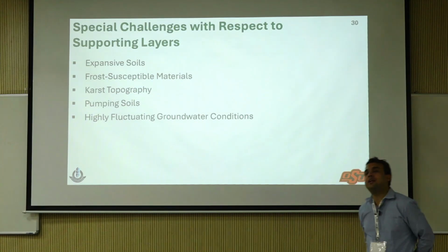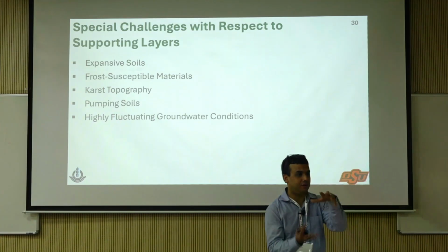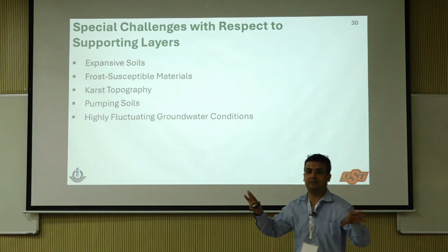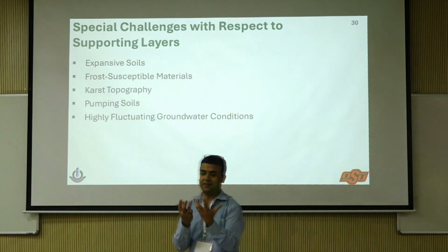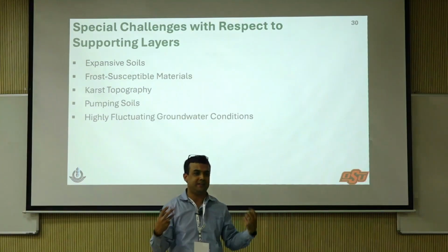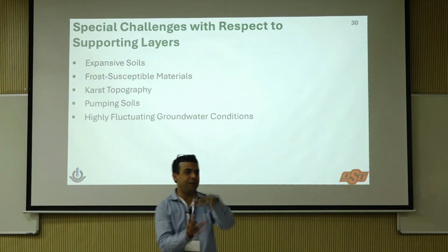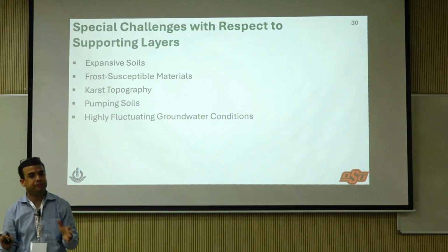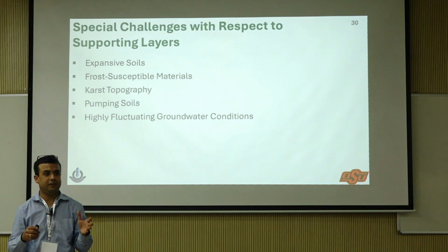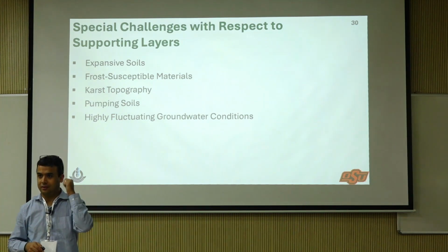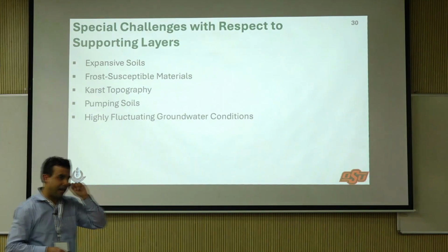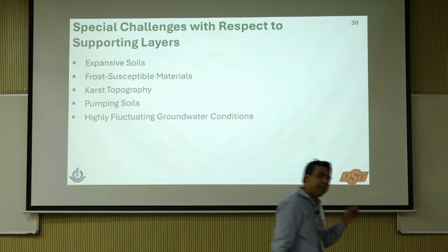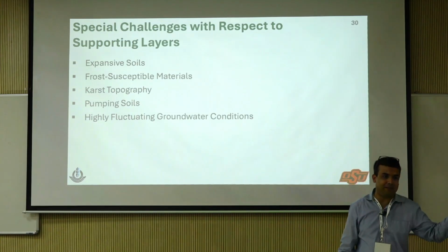Oh, so you're talking about the ability to capture freeze thaw stresses. That's a different thing. I'm talking about when freezing will happen. Yes, you are right. If there are air voids, there is a cushioning effect, a shock absorber basically, so you can absorb some shock. But I'm not talking about that. I'm talking about when frost is a problem. Frost heave is a problem. Water, low temperature, and the other is that the layer should have enough permeability for water to move through it, right?